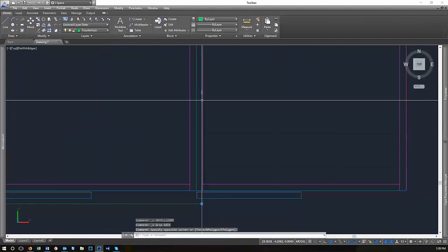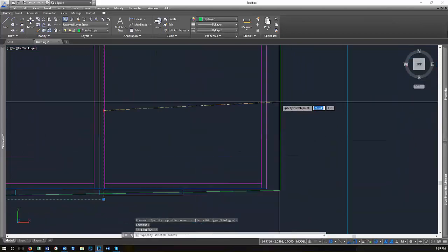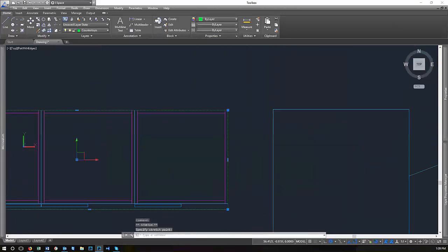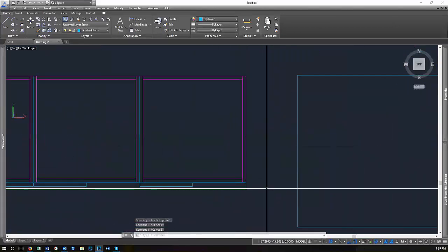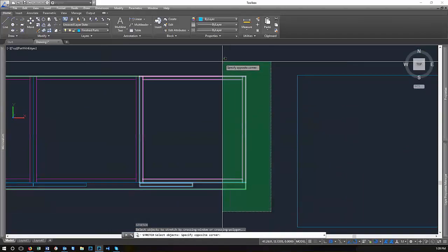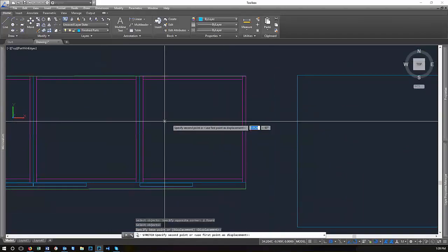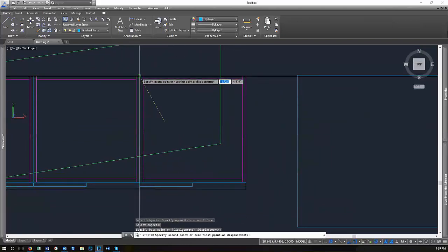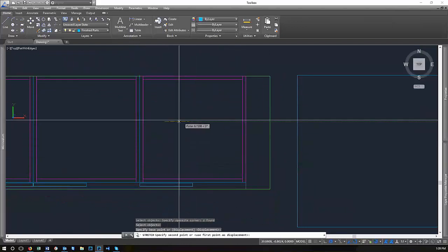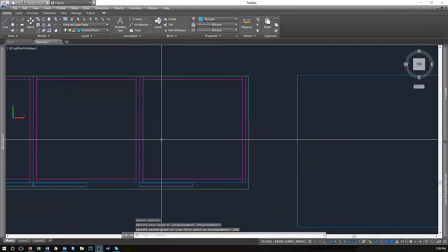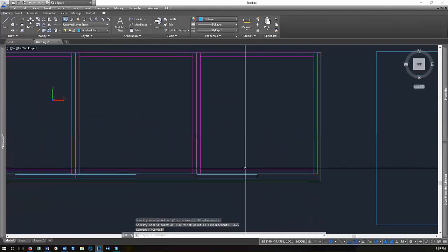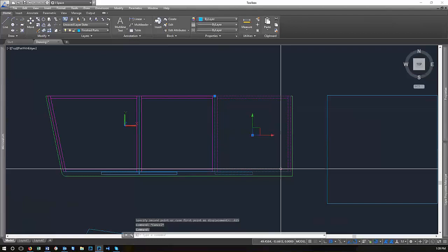Drag that out to the perpendicular spot instead of wherever I gripped it. Okay, got that. Now I can even use a stretch command over the top of this block. And if I do that, it's not going to do anything because I did not grab the grip point for that block. So it's not going to have any effect on the block, and I can put out my 0.625. Now I have my overhang on this cabinet, and I've got an additional cabinet on this set of this drawing.